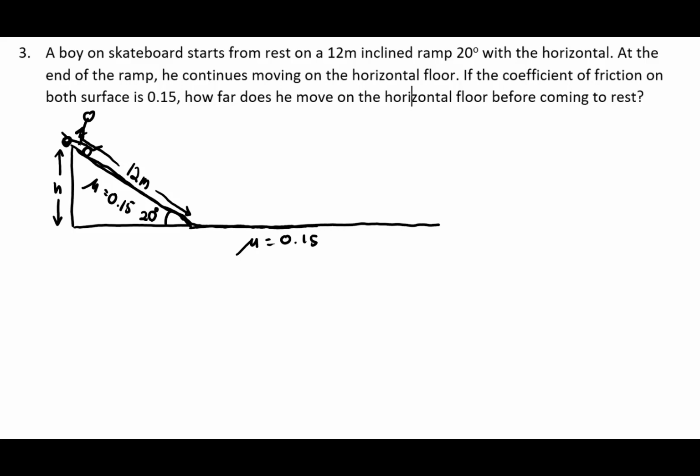Alright, from here I think we definitely have to do the free body diagram. What I have here, the friction is definitely going up, which is resisting the motion. We have a normal force right here. Then definitely the weight straight down, and our angle, which is in line with the normal force, theta over here is 20 degree. The acceleration is definitely going the other side of the friction.